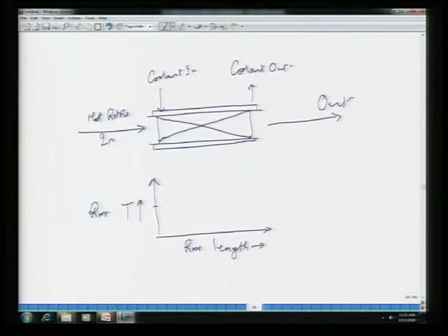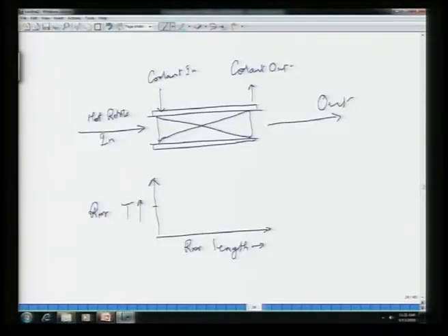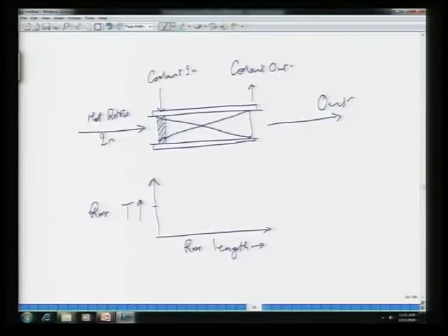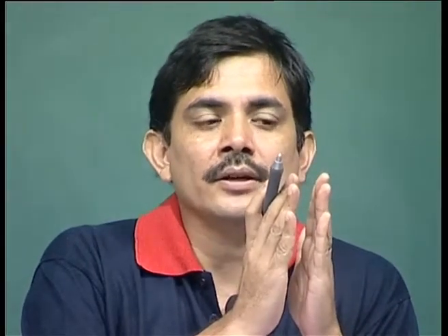Then what happens is, because the reactant is cold and or not hot enough, the reaction rate at the beginning of the plug is actually less than the amount of heat that gets removed from that plug. So, let us just focus on this initial segment. In this segment, the reactant is not hot enough, therefore the reaction rate is not high enough, and the coolant is cold, therefore a large amount of heat is getting removed. So, the amount of heat released inside the plug is less than the amount of heat removed by heat transfer. So, temperature will actually go down.